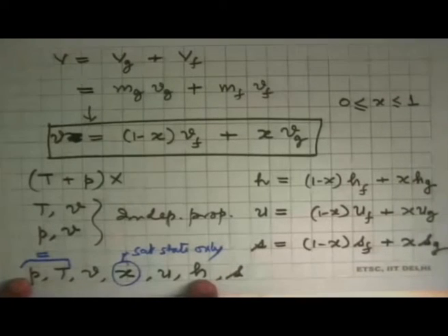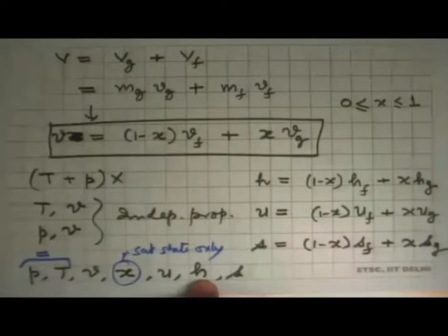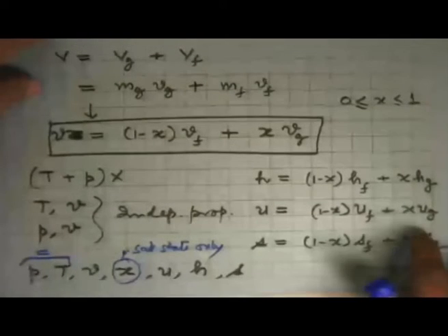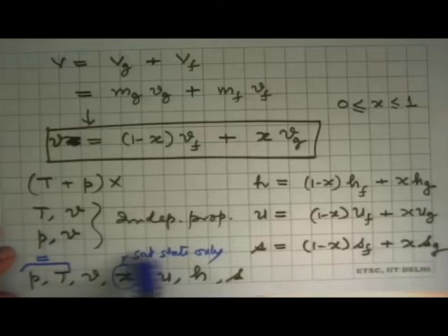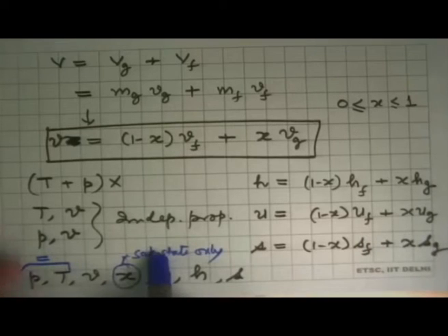If T and H are given, again, the state is completely defined. We can get all the other properties. The care that has to be taken, as we have seen now, is if it is a saturated state, P and T are not independent properties.